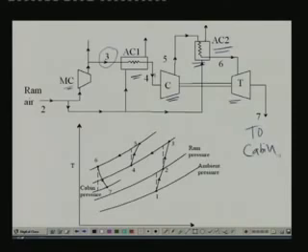Okay, so you can see the difference between the simple system and the bootstrap system. Here the power output of the turbine is used for running the compressor, and the ram air is used for cooling air cooler 1 and air cooler 2. The same ram air is used. So, obviously you can see that this system is not really good for ground cooling, because when it is on the ground you do not have any ram air, so the air coolers cannot be cooled. So, normally you do not use this system for ground cooling, you normally use it for high speed, high altitude flights.